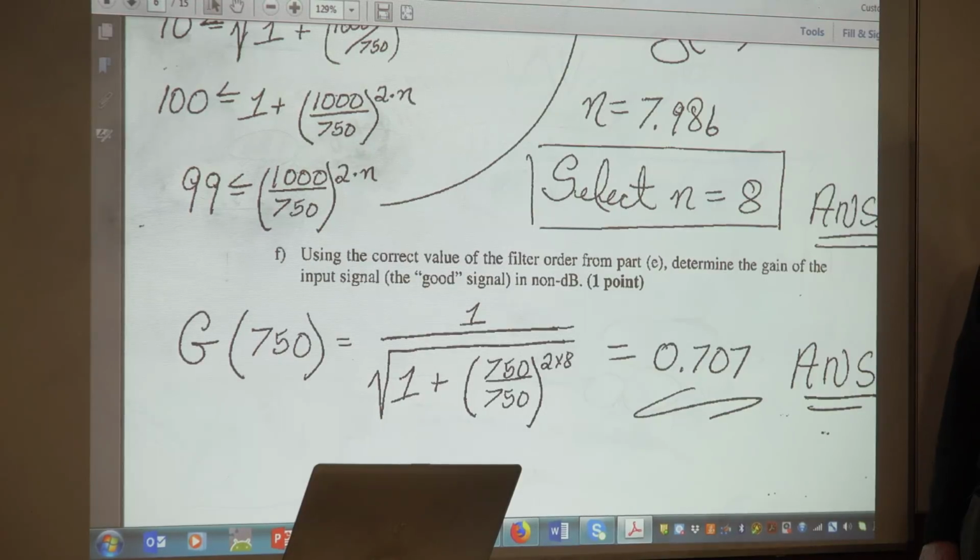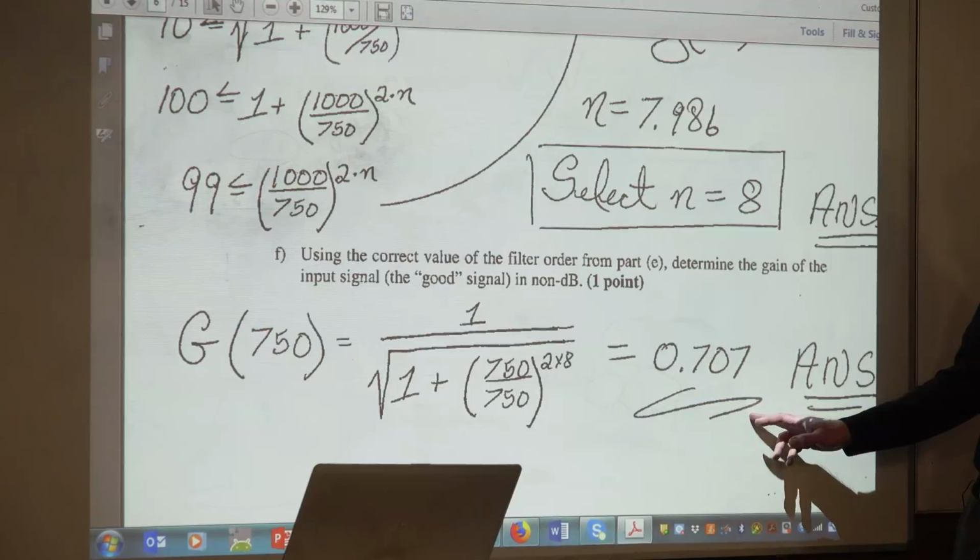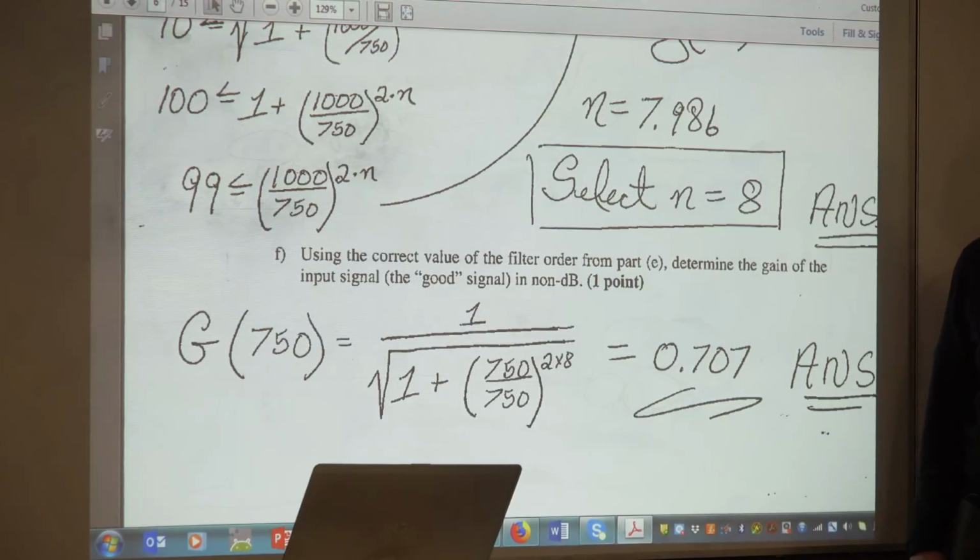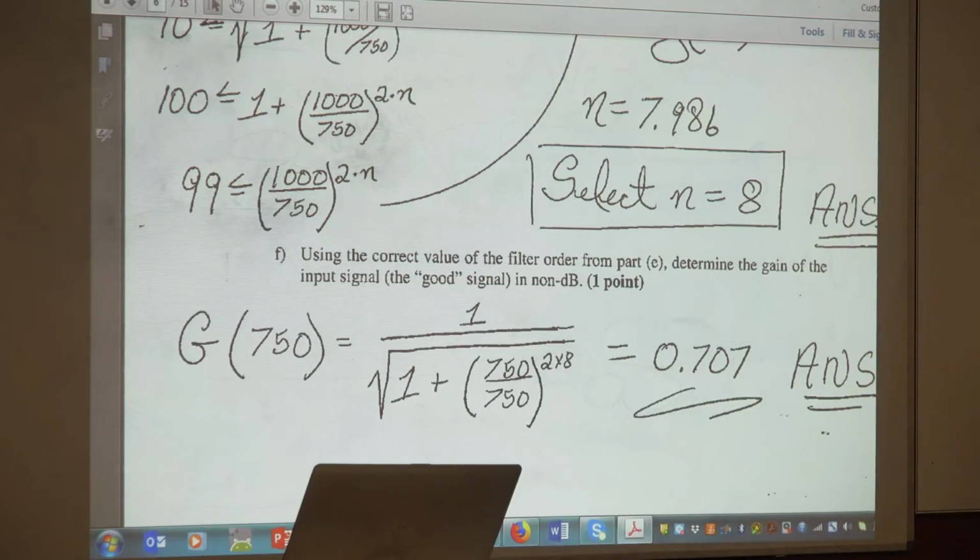Right, well, we know the slope, so help me out. You're bringing up a very good point. In this scenario here, we have an 8th order filter. We know the Bode plot. We know that the slope is 6 dB per octave per order. This is 8th order. So, yeah, we could test out every frequency, but there's also equations that would give us